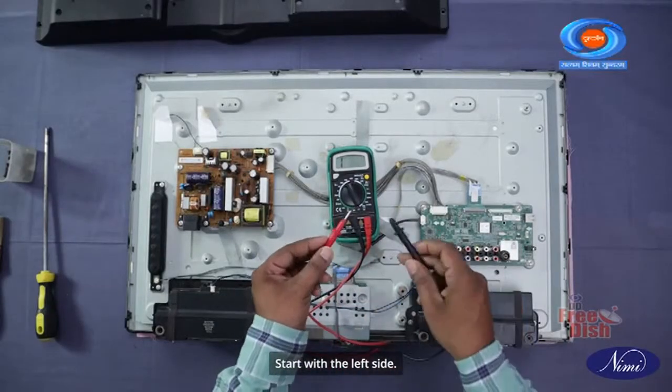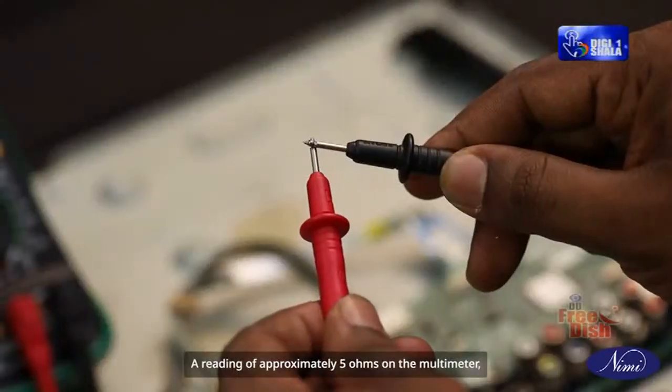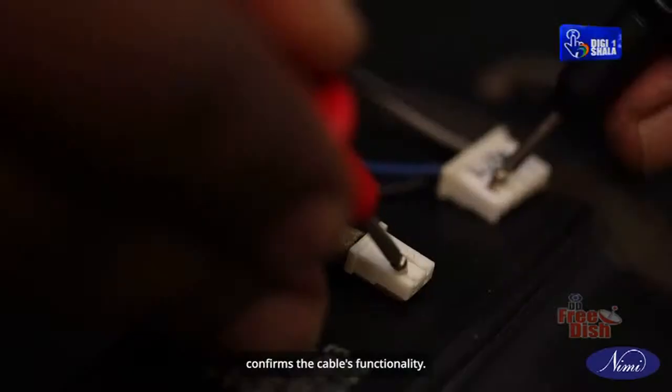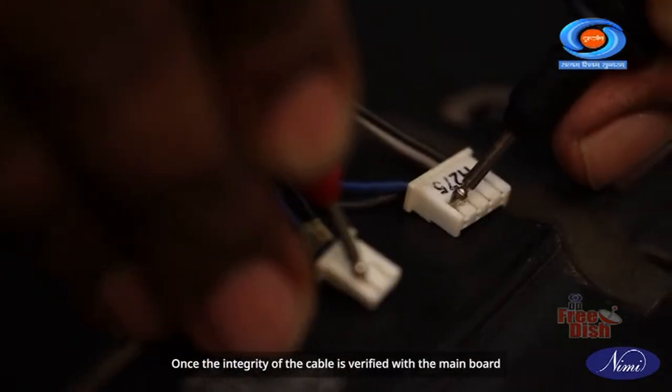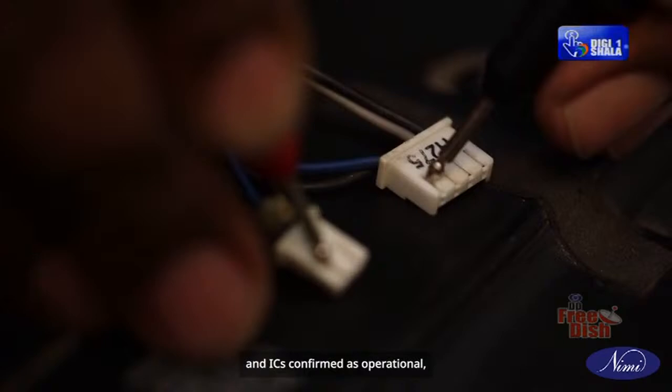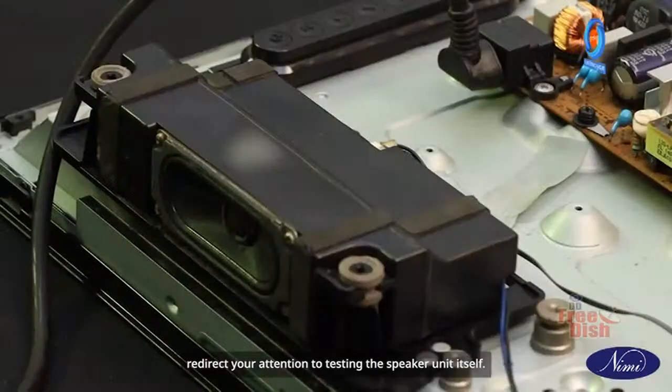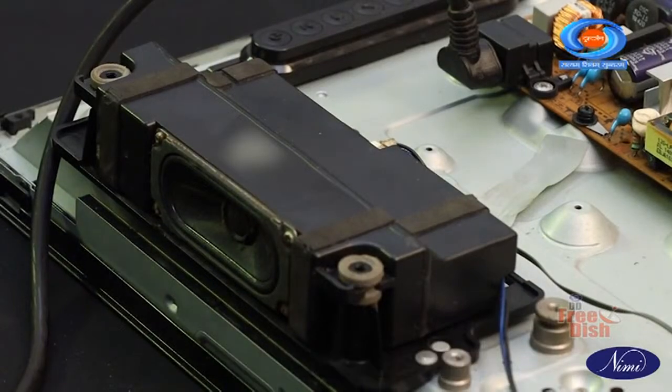Start with the left side. A reading of approximately 5 ohms on the multimeter, accompanied by sound output, confirms the cable's functionality. Once the integrity of the cable is verified with the mainboard and ICs confirmed as operational, redirect your attention to testing the speaker unit itself.